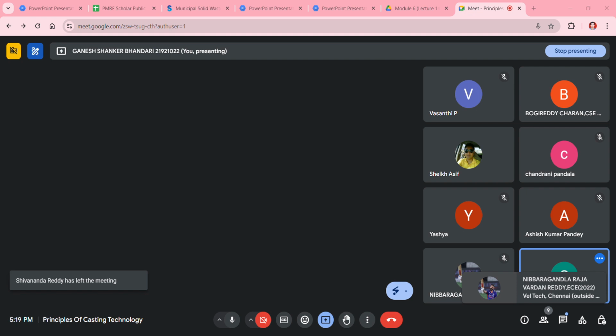So in case of the stationary container system, the formula will be TW equal to NW, which we had already calculated, the number of trips per week, into PSCS, the pickup time, which we have calculated as 1.22 hours, plus S plus A plus BX, divided by H into 1 minus W. That formula we can use for estimating the time required per week, but we are not considering the distance between the last container site and your disposal site.